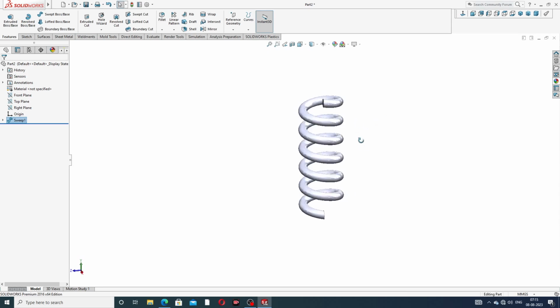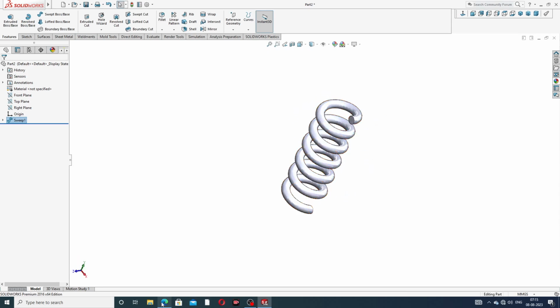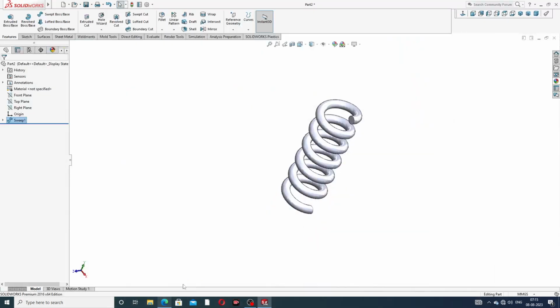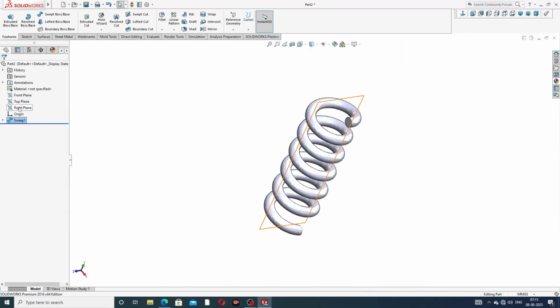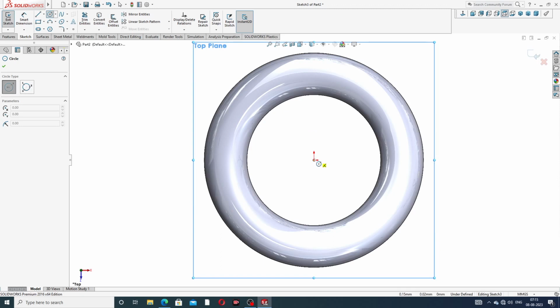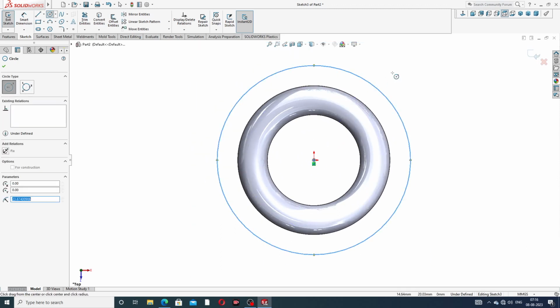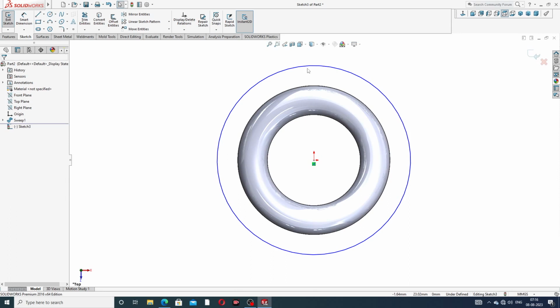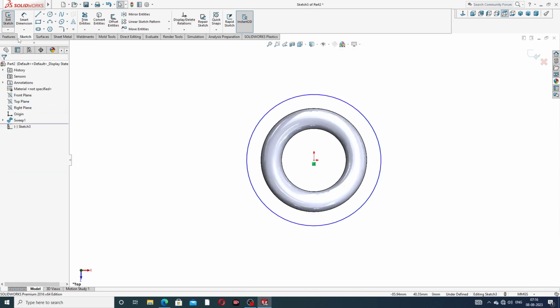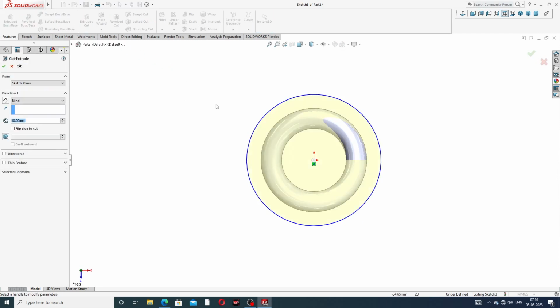Okay, this is perfect. Next, some cuts here: cut here, this and back side is this. Okay, both are cut here. Select a plane, the top plane, sketch normal, and draw a circle. The circle is drawn here; any diameter, it is not mentioned here. Okay, and extrude cut is applied here.